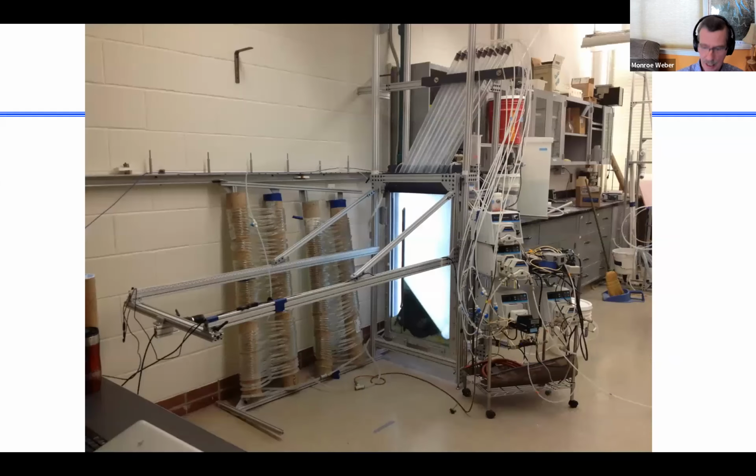So there it is. This system has a flocculator, and you should chuckle to yourself and say, Monroe, you didn't teach us how to design these flocculators. They're just a bunch of tubes wrapped around some cardboard. And this is a laminar flow tube flocculator that works for really low flow rates. Doesn't make sense for municipal plants, but it works in the lab.